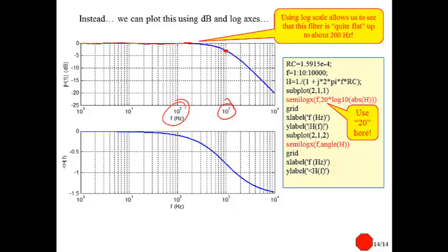So I'll try to write that down here. Minus 3 dB equals half power point. And we'll see later on that that is also called the cutoff frequency of this filter. So we take that minus 3 dB point and view that as this is the stop band, this is the pass band. Even though we're getting some attenuation, again, this is not ideal.